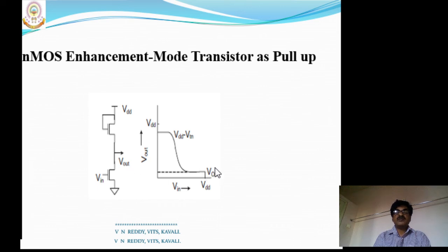As in the previous case, the voltage here is VTN, that is the threshold voltage amount we can observe at the output. So in both the logical low and logical high cases, you can observe voltage degradation. We are not getting perfect voltage values. That is one drawback here.